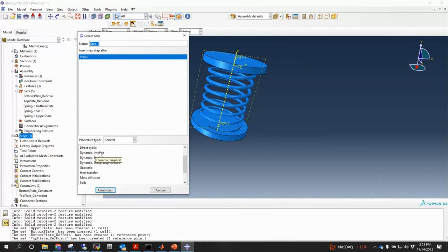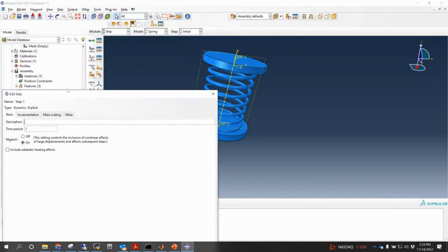I've heard of the materials. Yeah, when the materials deform, like you apply a load, and then it deforms super slow, right? Like viscous behavior. How much time do you need to model that? Like hours. It's a process that lasts hours. And in that way, it's easier to do it using implicit analysis, right? But for our things that are gonna last less than a second, let's use explicit, all right?